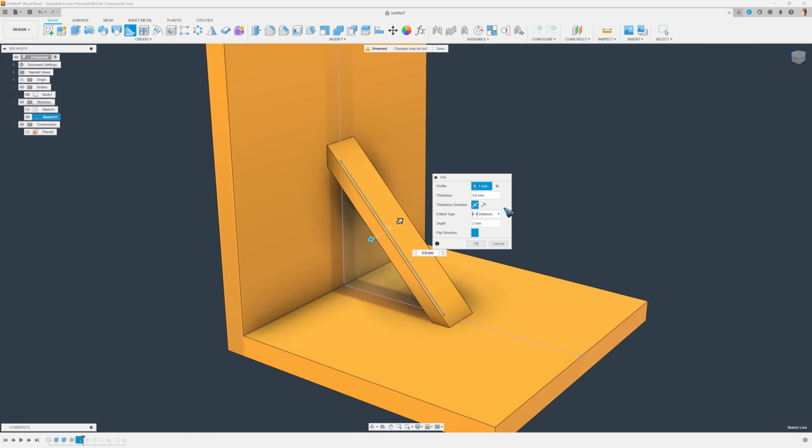Well, this was actually it. Of course, we now simply made a straight rib, but you can make any nice curved surface, what have you. One more thing to notice is that unlike with many other commands, we do not have a box to select a new body or even a new component. The only thing that the rib can do is join. So it now has been added to the existing body.